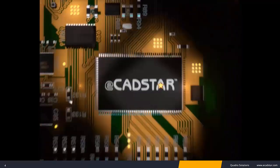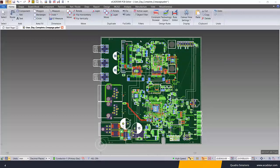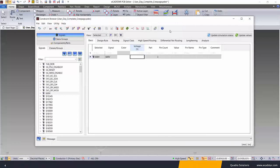So the Creepage Checker within eCADSTAR's PCB editor is a powerful tool, and it's so much more than a basic clearance check. The voltage difference can also be changed based on the requirements for a voltage difference range. The flexibility and sophistication is down to the user control. So in this design, I've maximised input voltage to 600 volts at the power connector of our demo PCB.